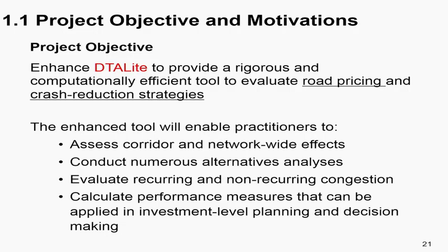Okay. Through all this process, we hope we can help you to enable the DTALite, and to make sure that you understand that DTALite is basically a capacitated dynamic traffic assignment, which means we mainly consider the capacity impact from the upstream bottleneck to the downstream bottleneck.